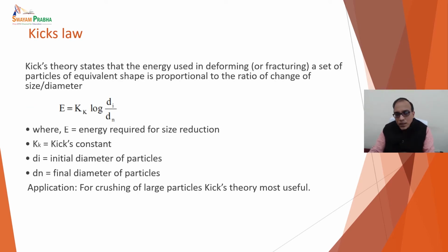Kick's law. Kick's theory states that the energy used in deforming or fracturing a set of particles of equivalent shape is proportional to the ratio of change of size and diameter. So E is equal to K_K log Di upon Dn.